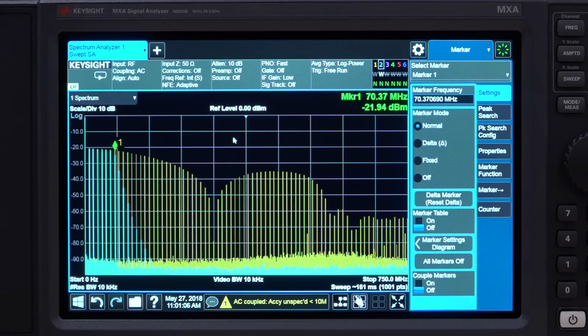it makes perfect sense. Now, because I can do this, I should be able to measure filters with much higher bandwidth because there is so much signal content at high frequencies coming from this arbitrary waveform generator. And this is yet another advantage of having very narrow pulses and broad spectrum production directly from the unit itself.